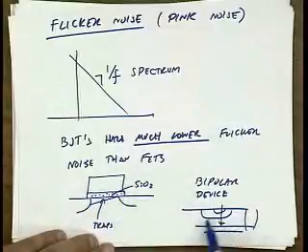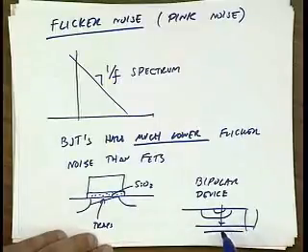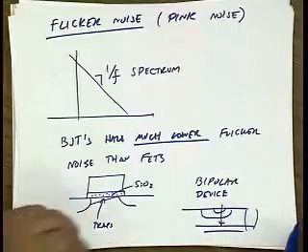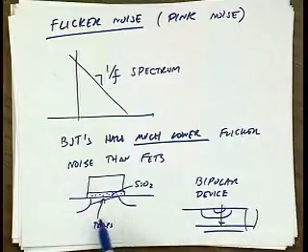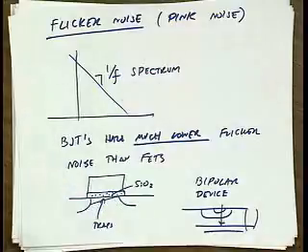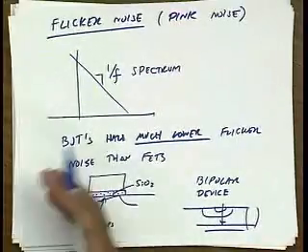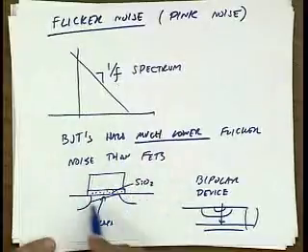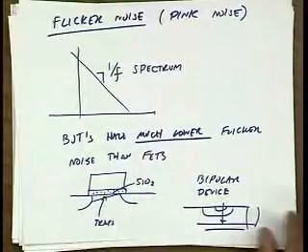If you go deep in the body of the transistor, there are much fewer trap sites, and therefore the flicker noise is much lower. So this is the reason why bipolar devices have much lower flicker noise, and why depletion PMOS devices in the old days had much lower flicker noise than NMOS devices, because the channel was actually forming under the surface.